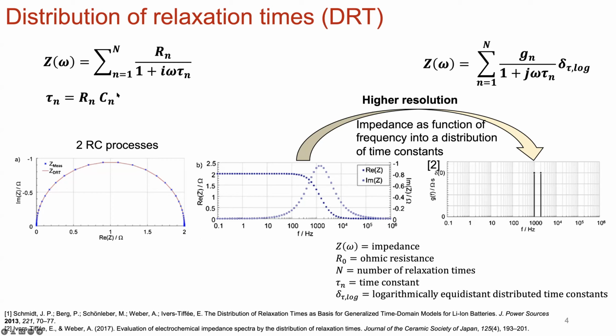And we've talked previously about, in parallel, RC plus RC would look something like this, where you sum over all the elements in your equivalent circuit, and you have the time constants of that particular process out, right? So you could do that. You can plot the Bode plot. You get the typical frequency here as well, okay?